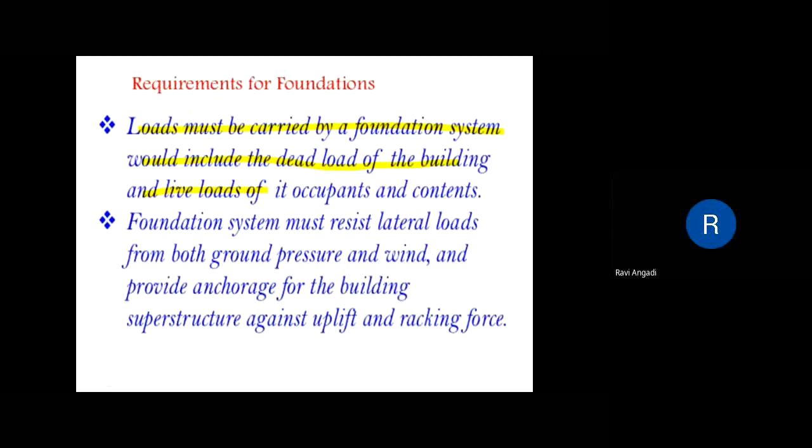So before designing the foundation, you need to consider all the loads coming on the structure. Then the foundation system must resist lateral loads from both ground pressure and wind, and also provide anchorage for the building superstructure against uplift and raking force.